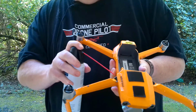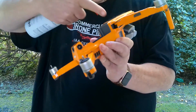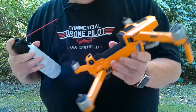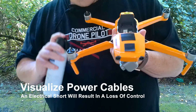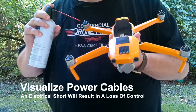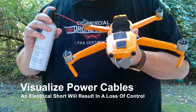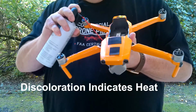Look at the portions where the rotor arms meet and just visually confirm that the cables that go from the circuit board to the rotor blades, that cable is not worn or frayed or discolored in any way.